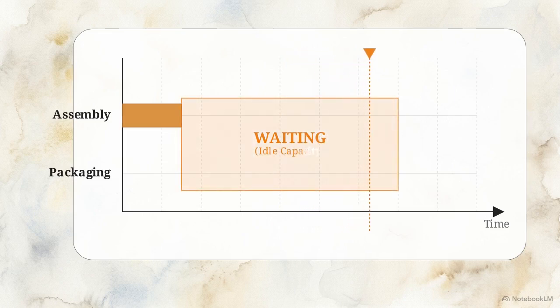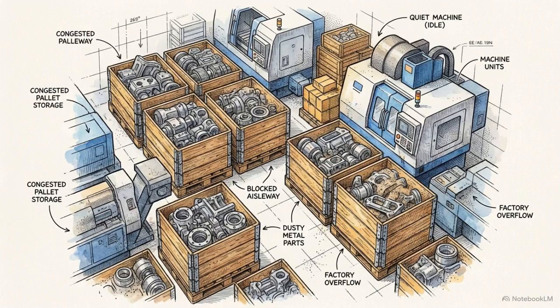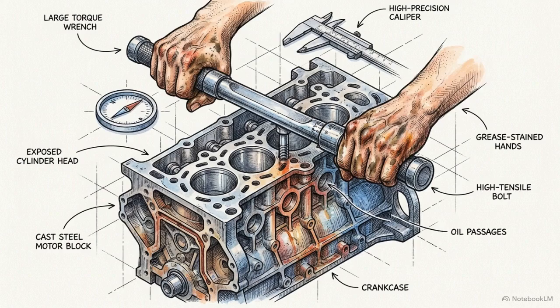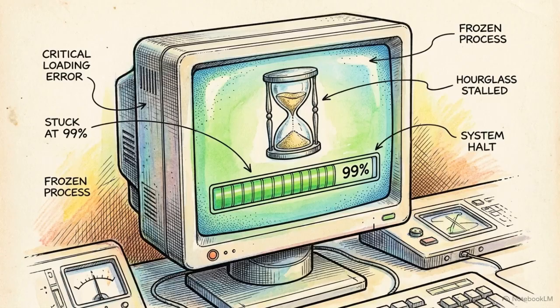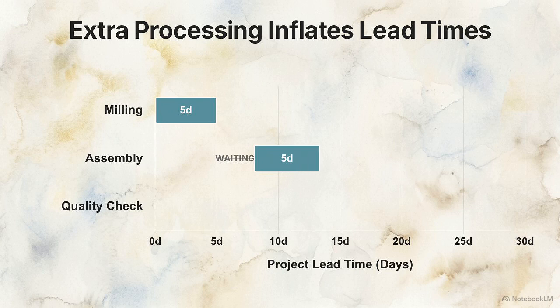Those bottlenecks inevitably create waiting. This is the idle time between steps, where capacity sits entirely unused. This dead space typically accumulates at systemic cue points: physical handoffs, manager approvals, machine setups, maintenance breakdowns, and batch logic processing. Categorizing idle time as waiting without investigating the root cause is a mistake. Often, operators are forced to wait because of inflexible batch logic.